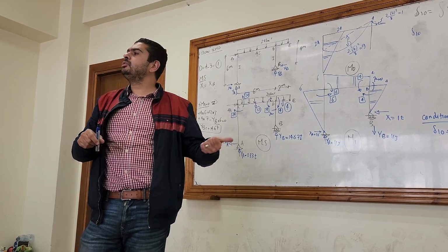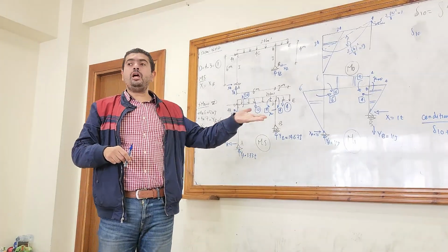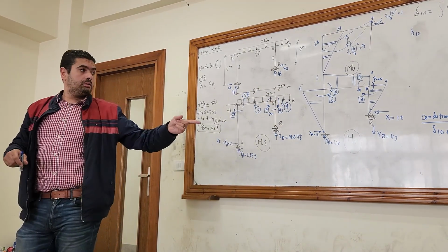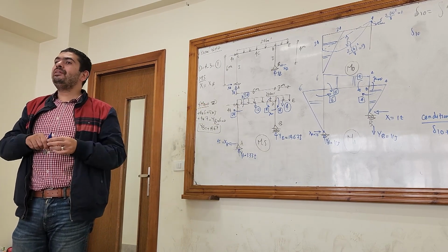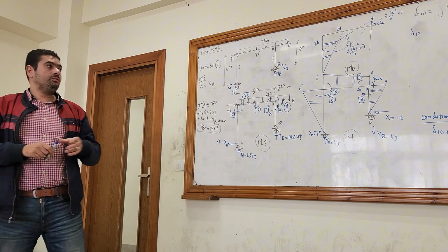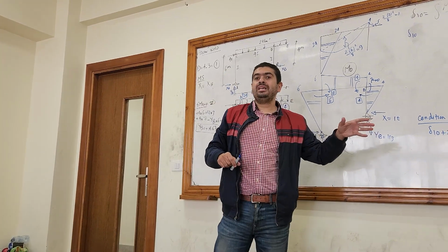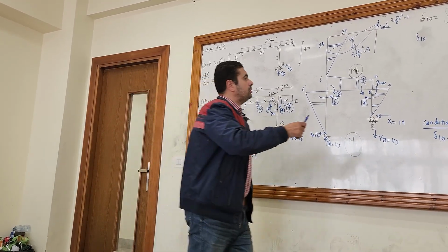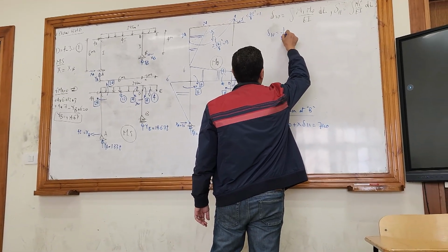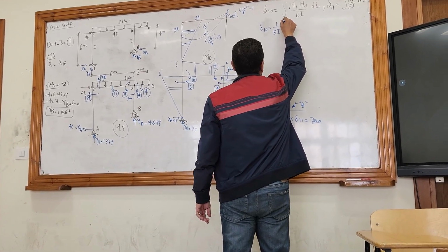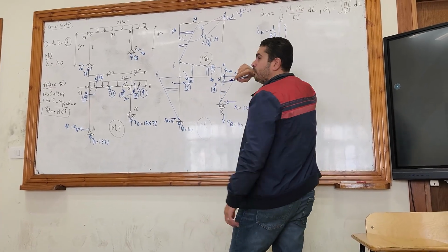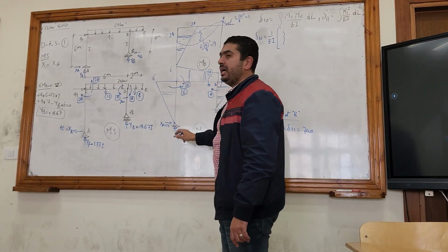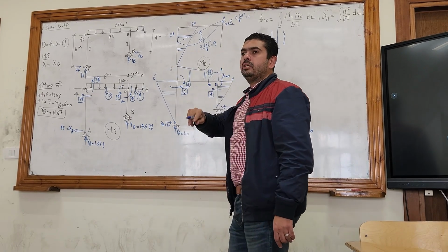But here in the indeterminate structure, there are a lot of steps to do after you calculate the delta 1 node. You still will calculate x from the condition, and then you will draw the bending moment diagram. So this is not the end of the example as in the determinate structure. Okay? So delta 1 node, 1 over EI outside, and then a big bracket, and then a small bracket for each member. For the vertical member, here it's a triangle with a triangle, so linear with linear.